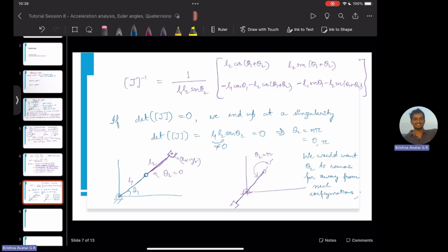So the farthest from this position, of course, implies that thetas should be, say, closer. In general, just speaking, if theta 2 is somewhere around 90 degrees, those are the locations where the second link is farthest from attaining that singularity, isn't it?